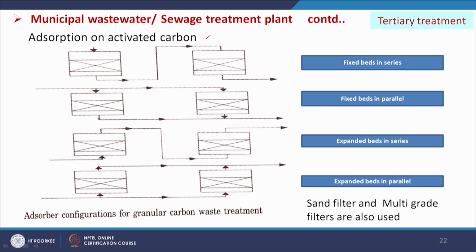Here these are fixed beds in series. Water is coming from the top, from the bottom it is getting out and again enters at the top, so there are a number of units in series. Fixed beds in series. Now, fixed beds in parallel, in both the units simultaneously water is getting entry and getting out from the bottom. Expanded beds in series.